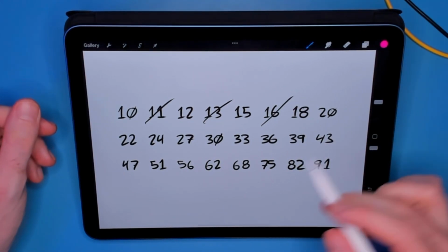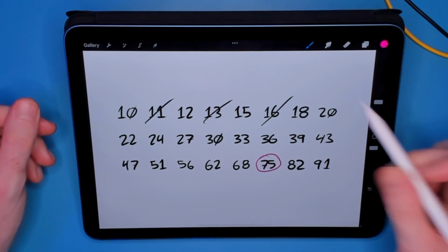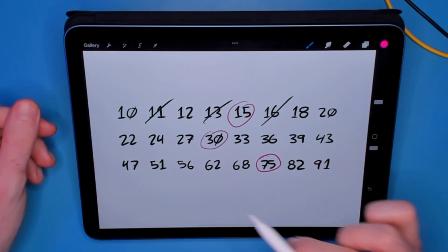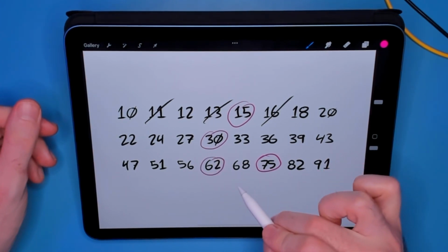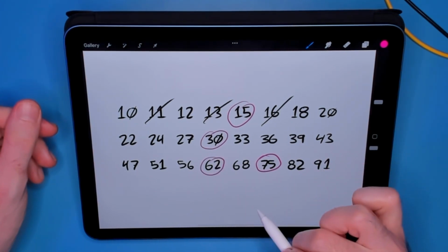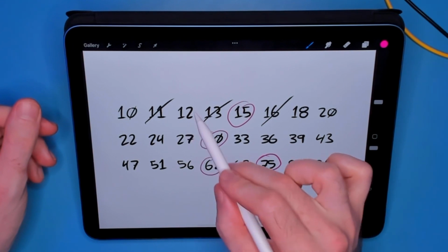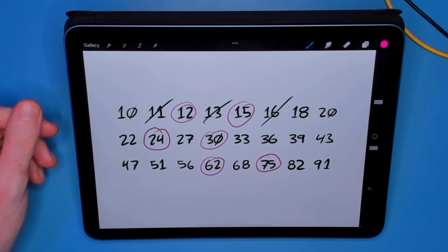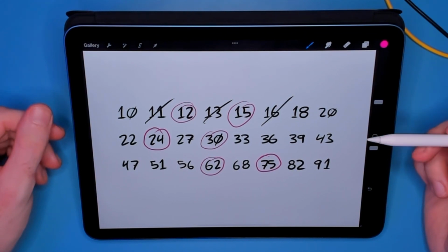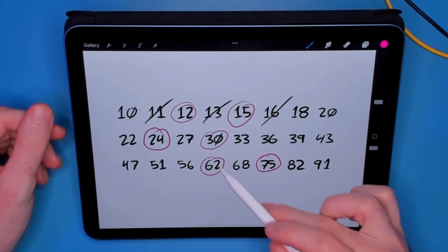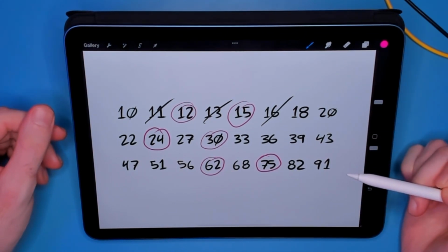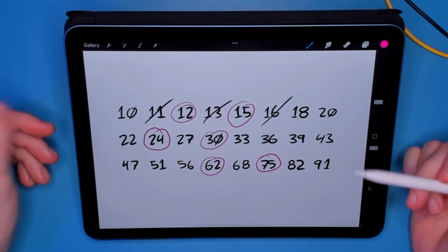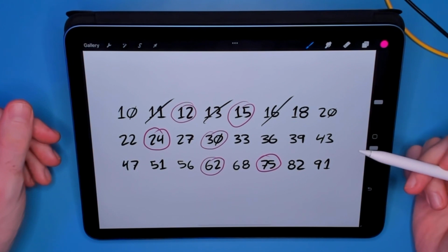So my idea was to start with 750, double that to 1500, double that to 3000, double that to 6000, well, okay, that's not quite 6,000, but close enough. Double that to 12,000, and finally double that to 24,000. I could have used a pair of 12K resistors in parallel to make up the missing 6K, but I decided to just stick with it because it worked well enough, and I plan on building a better DAC later on anyway.